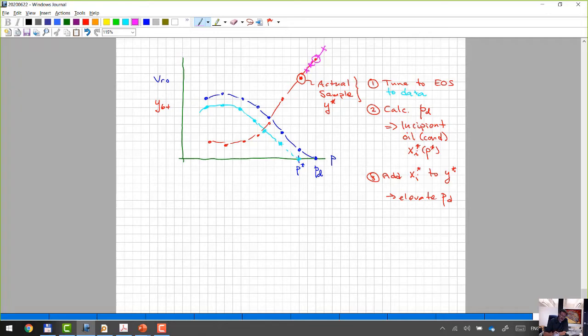And then, maybe there's an initial reservoir pressure limit or not. I don't know, but there probably is, since you say you went below the dew point. So you basically create the curve that you need. And then what you're going to have to do is just make an estimate and say that, okay, I go to the initial reservoir pressure. We knew that. Or you go to some CGR. You have to make some assumption, but you can do sensitivity to that initialization here, right? And if you deplete any of these, you're going to come down to this sample that you had here. That's what you're going to find.